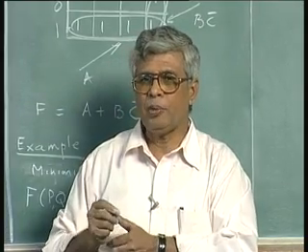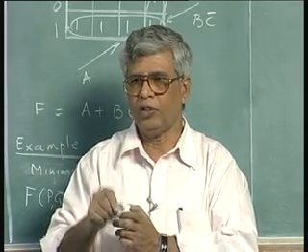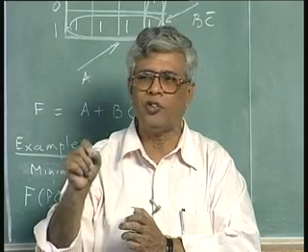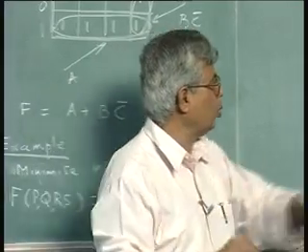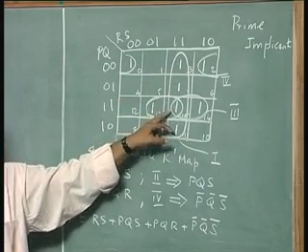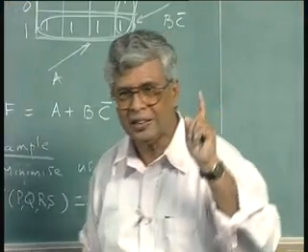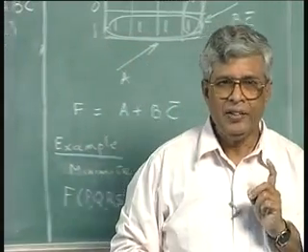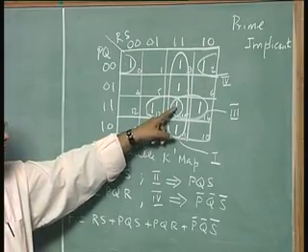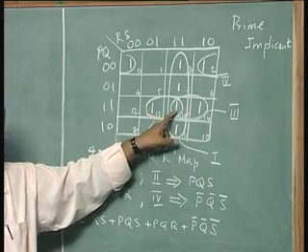and out of all the prime implicants, any prime implicant which is essential for the final representation. I told you two things, we have to make sure all ones should be covered irrespective of the fact that one can be covered more than once. For example, this one has been covered 3 times, this was covered along with this, covered along with this, so that is okay. But each time we have included at least one cell which had not been combined earlier, is it not? When I wrote this number 2 term, this one has been included new. When I wrote 3 term, I included this one new.